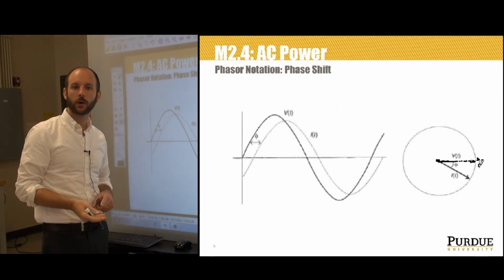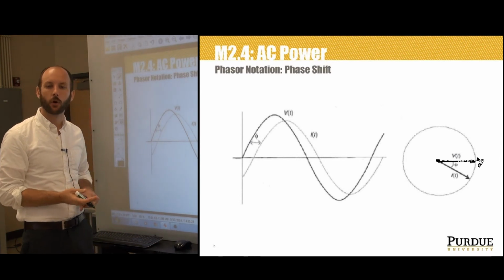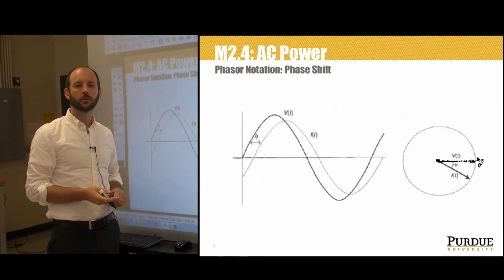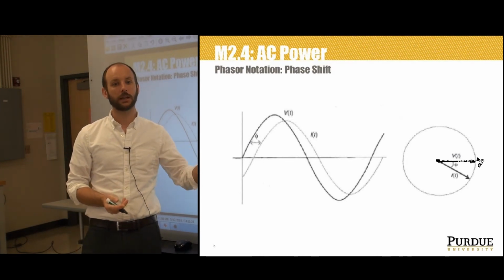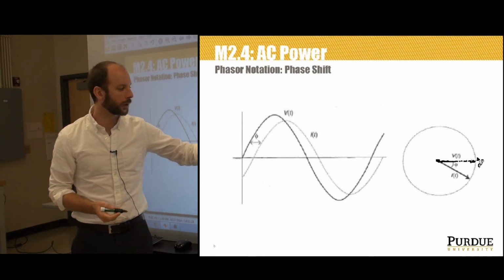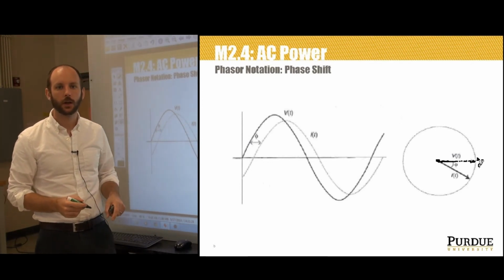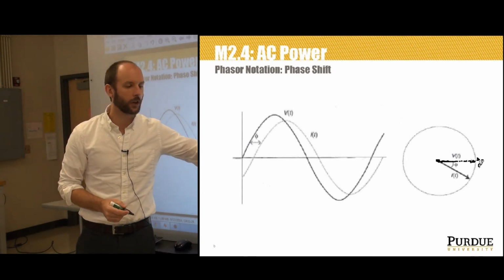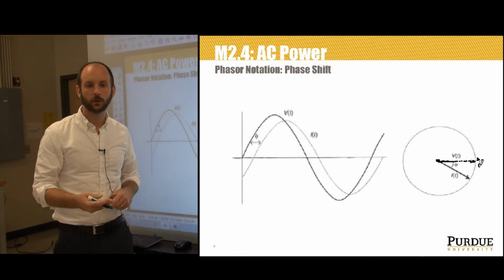And we're going to take it as the reference phasor in this case because it has a zero angle. This is very common, taking the voltage as the reference phasor. In reality, remember that for a sinusoidal quantity, this voltage phasor is spinning at a constant rate in a counterclockwise direction. But because we're only interested in the relative displacement between the two, we can ignore that spinning.